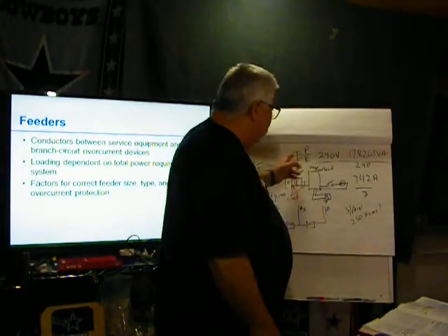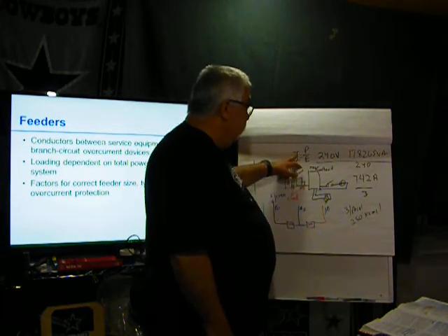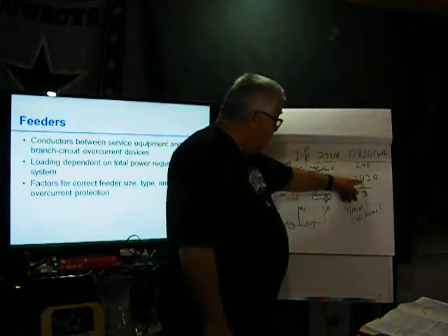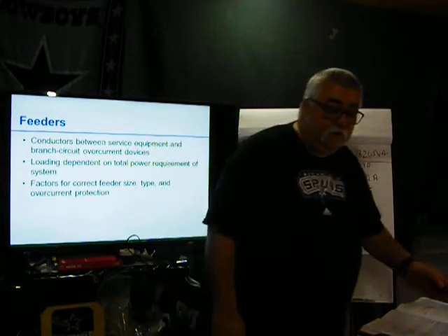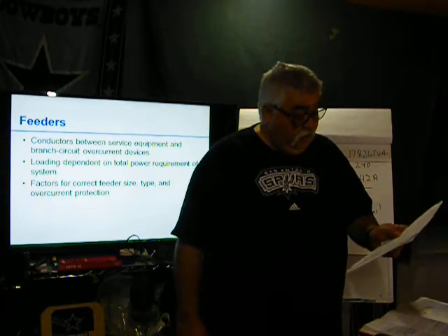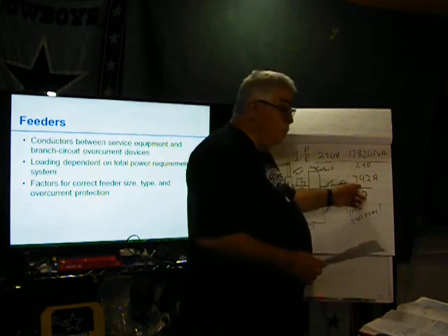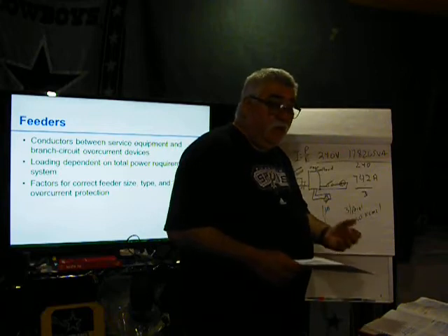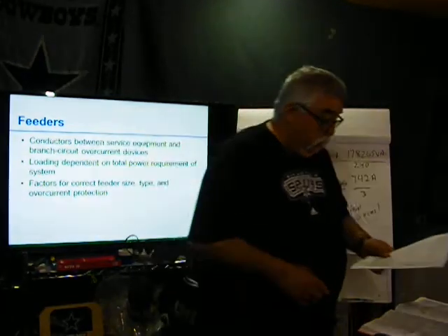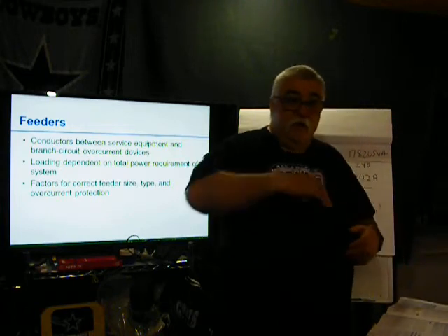Let's say I got an example here. How do we size a feeder? Well, power divided by voltage equals my amps. So I'll give you an example here. Now I got 742 amps. I go to table 310.15(B)(16) and I go down all the way to the 2000 kcmil, and that wire does 655 amps. I got 700. The last thing I want to be messing with is a 2000 kcmil. I don't like messing with 4/0 or bigger wires. Even though I've done it before, not fun. So I would put them in parallel to downsize my wires.